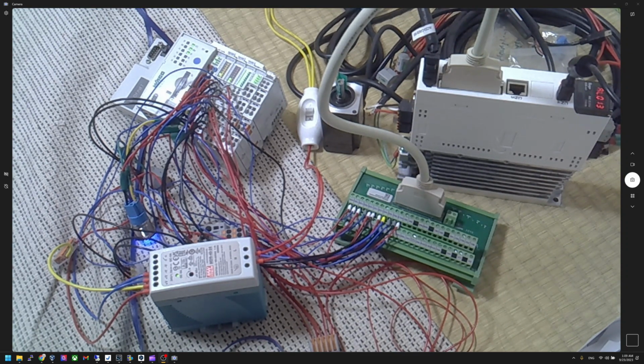Codesys runtime. So here I have a DIO module, and an AI module, AO module, and I only use the DIO this time, and this cable is wired to the IO terminal board, and this IO terminal board is connected to the drive, and here's the power.